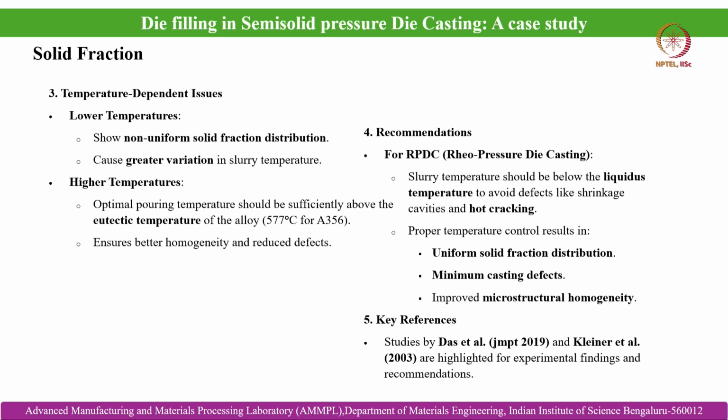That is what I have discussed with you earlier also, because if we choose a particular melt pouring temperature and it results in the melt temperature dropping during the die filling stage below the eutectic temperature of the alloy, in this case 577 degree, then the solid network which gets built within the solidifying melt becomes so thick that flow becomes impossible, and that is why it is prone to generate defects within the solidified parts. So it is preferred to be above eutectic temperature always within the filling stage of the component.